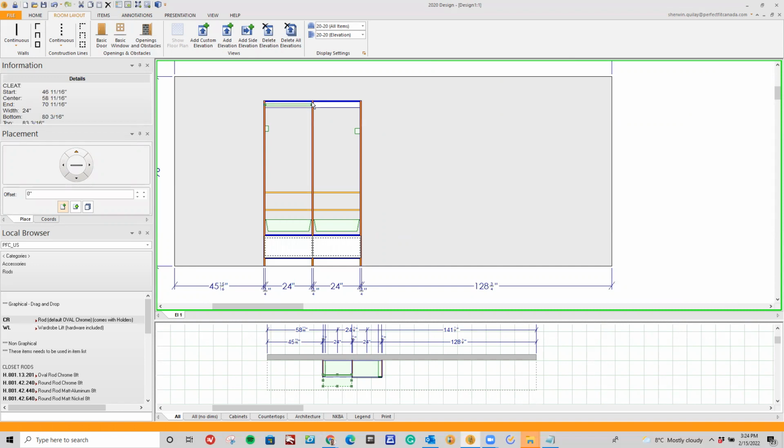Each closet rod has got 2 oval chrome rod or round rod holders for the rod itself. So we're going to subtract 24 inches less the holders. So it'll be roughly around 24 3/8. Therefore, installers do not need to cut any wall rails or hanging rods on site. We will have everything pre-cut. The only cutting the installer will need to do on site is if they have to scribe it to the wall, any bridge shelves, or any fillers. Otherwise, there'll be minimal cutting involved, which is a fantastic program.